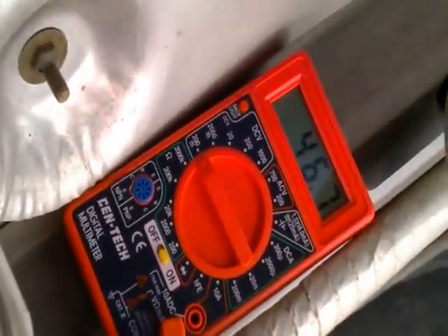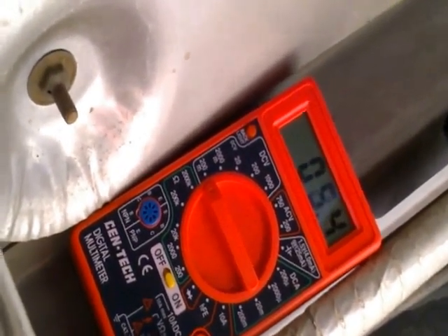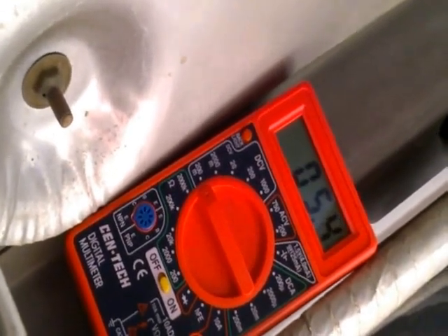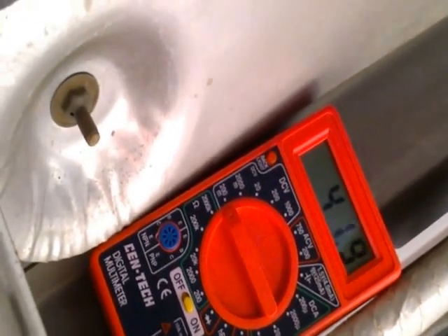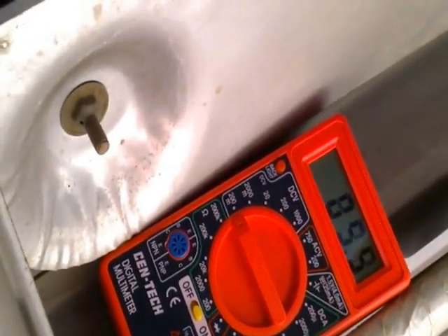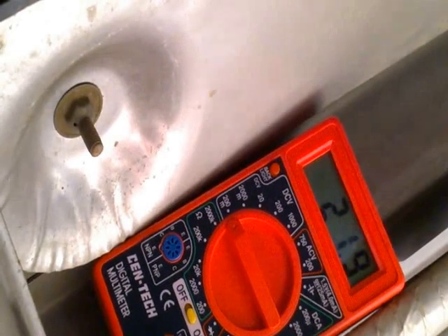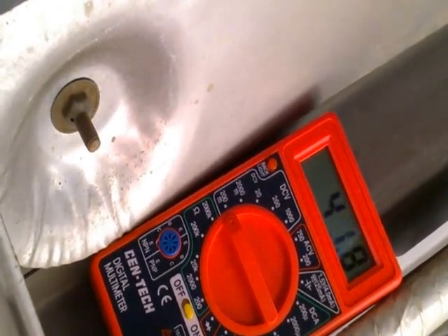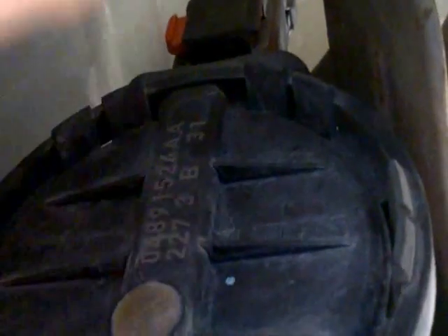So now let me show you. I'm gonna zoom in so you can see the voltage is fluctuating. Like I said, it's pulse width modulated. The computer is controlling the ground side. So the max voltage, as you can see, is jumping around. It goes from 40 something, and then back to 5, then 0. So like I said, this is pulse width modulated, and as you can hear, the solenoid is clicking. But the problem with this natural vacuum leak detector is the switch. The switch is stuck open.